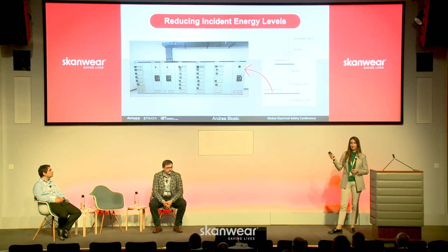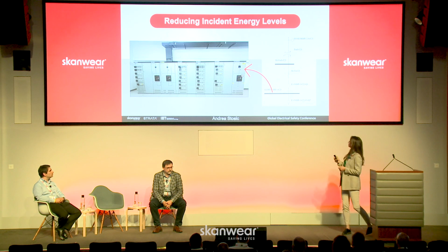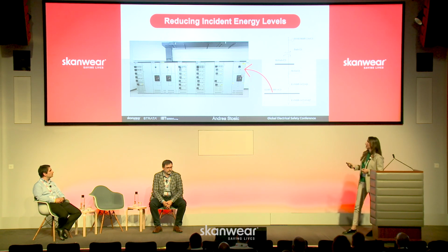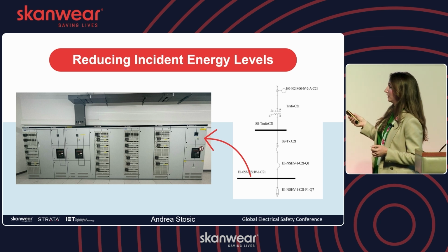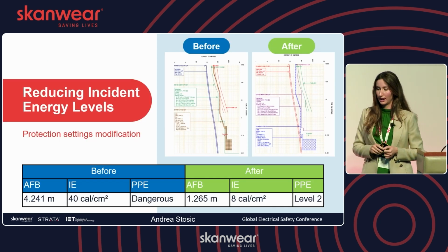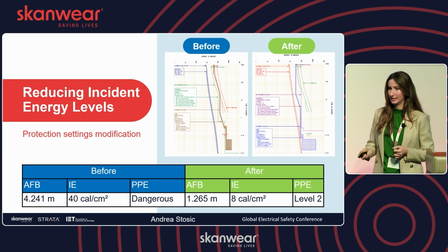And on the schematic diagram on the right, you can see how the switchboard is represented by a bus bar. What you cannot see on the picture, but you can see on the schematic, is that this switchboard is basically right downstream of a transformer. This is a medium voltage to low voltage transformer. There is a medium voltage relay and a breaker in the upstream medium voltage switchboard. Again, you cannot see it on the picture, but you can see a low voltage circuit breaker, as in the incomer circuit breaker here.